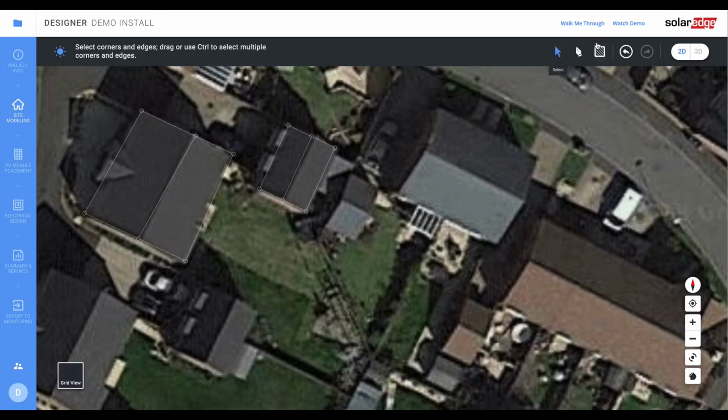So what I would do is draw out the obstacle to cover that peaked roof, or perhaps if you have a chimney, so the chimney sticks out around here, or you've got skylights or something, you would draw those obstacles on there, and that means when it does the space calculation, it knows that it can't do anything with that. So just good to keep that in mind.